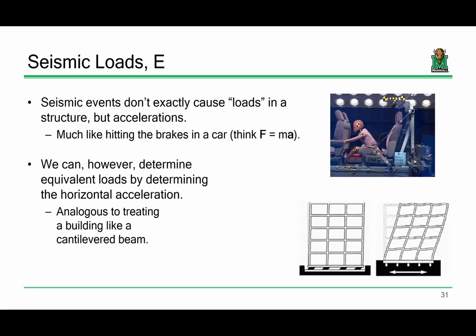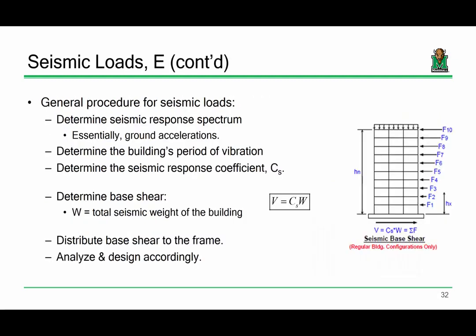And when an earthquake strikes, it's taking that building and moving it through an acceleration. The ground is going like this, and it's causing the building to accelerate. So force equals mass times acceleration, in general, will tell you how much force is being applied to the building. Now, it's a little more complicated than that, obviously, because there's a lot of math you have to do to get to those forces, and I think we're going to try and get there today.